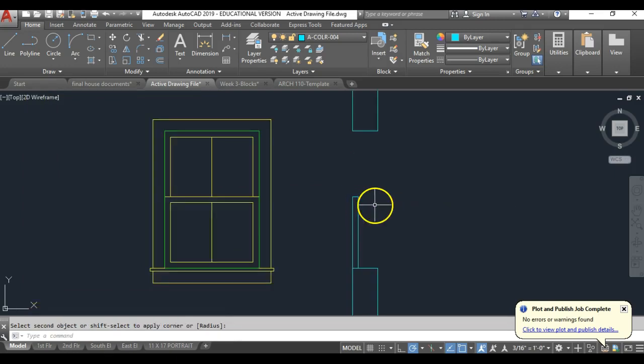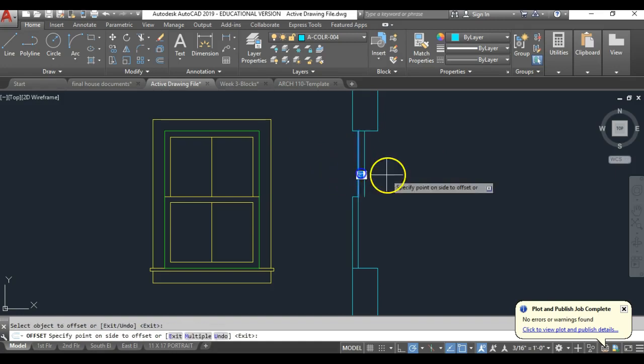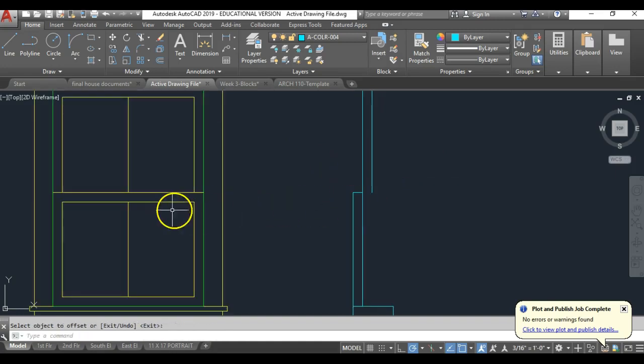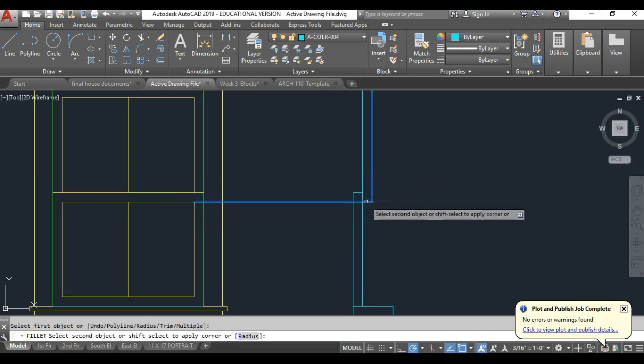And I know the top edge is going to be the inside to the inside of this, so it's going to come here. It's going to also be offset 2 inches to the inside. And it's also going to come down to this bottom line, which happens to be the same as all the thickness, which is 2. So I can either pull it down to, or I can just bring that line across and fillet it and trim things together either way. Now, I'm going to erase this.